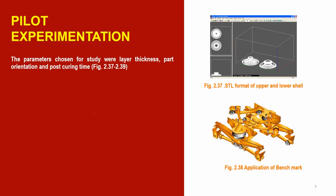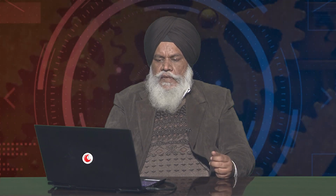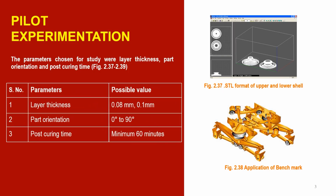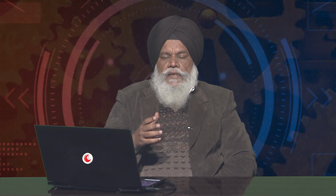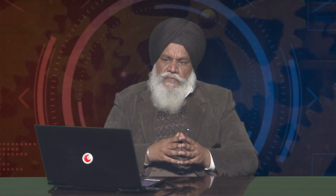So the physical part you can see over here. In this particular example, I am showing you one of the components that is used in the suspension system of the truck, right? So this is the component which is basically a pressure die casting component. But just imagine, let us say I am a vendor for a big company, and the company asked me to develop this type of component by pressure die casting, but they want to see some of the physical models. So this 3D printing can really be an aid in that case, that I can make some of the parts for the physical verification and then can use the conventional process for manufacturing.